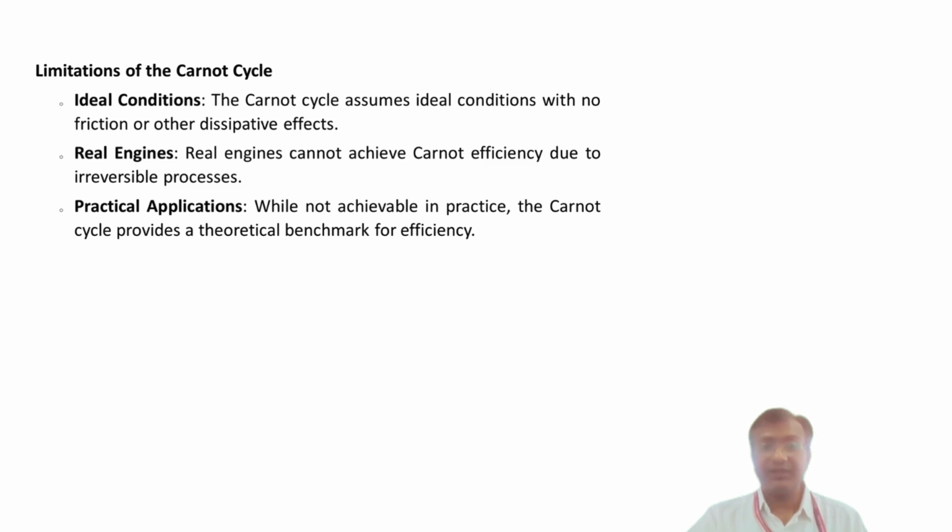Third, the Carnot cycle involves ideal gases or other idealized working substances that do not exist in reality. Real working substances have properties that deviate from the ideal behavior, such as real gases having van der Waals forces, and they may undergo phase change or may have other complexities. These deviations from the ideal behavior can affect the performance of the engine and make it less efficient than the Carnot cycle.